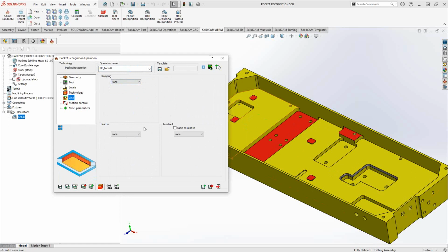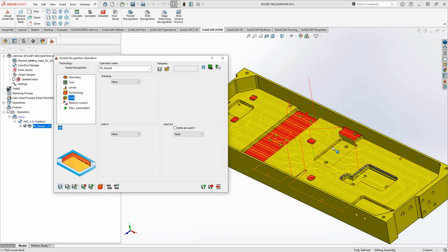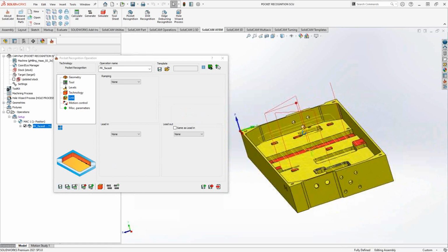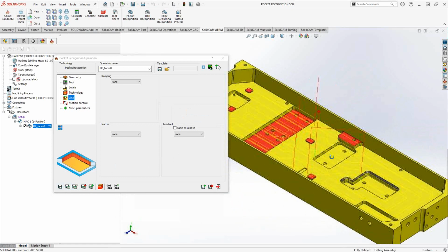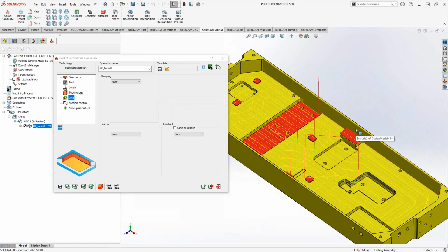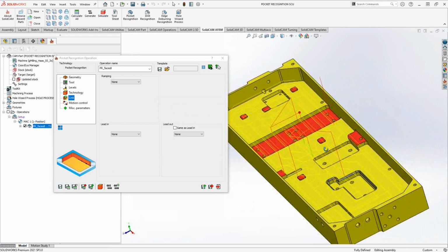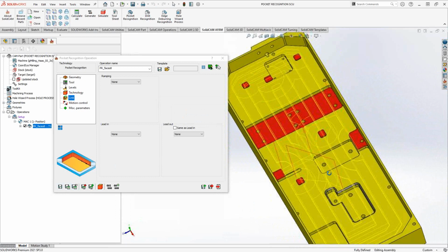But basically what you'll take away from this is you apply a set of pocketing rules to the overall part, and then when you click Save and Calculate, you'll get pockets for each one of those features. Now what's kind of unique about this is it knows it's doing multiple pockets as well. So it is actually doing a main pocket on the top here using basically this edge here.